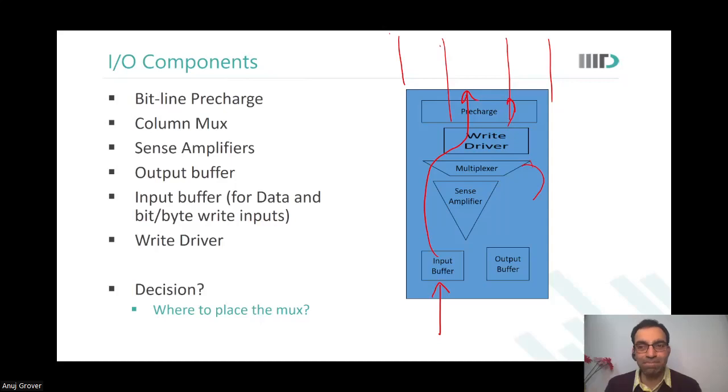Okay, sir. Shivendra? Yes, sir. Also, the leakage power will increase in this case. So why will we prefer this circuit? As soon as you increase the area, the leakage power would also increase. Yes, you're right. But because the performance would improve, that is why you may want to use this circuit. The writability would improve, write time would improve. For the sense amplifier, if you put it up there, the time at which you can trigger the sense amplifier will improve. The delay would reduce.